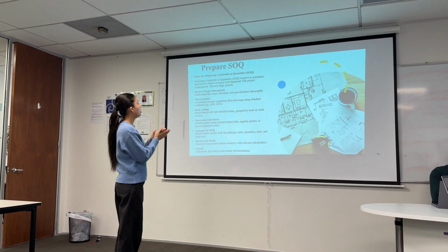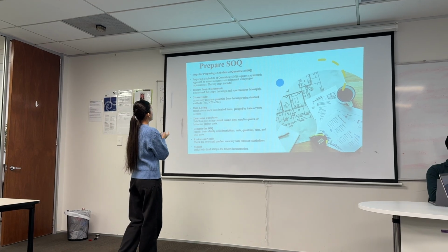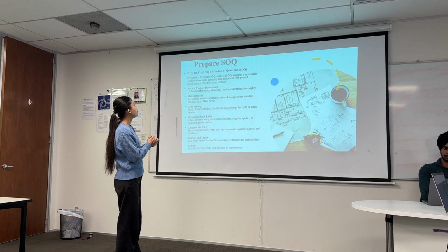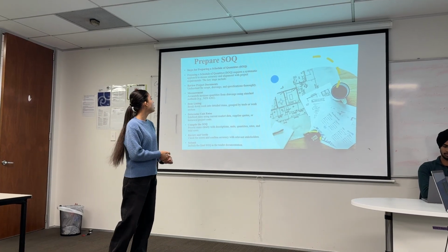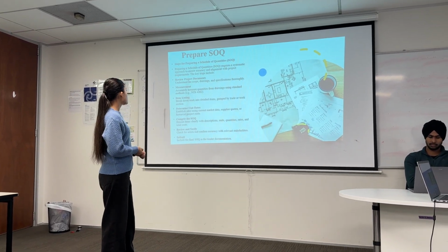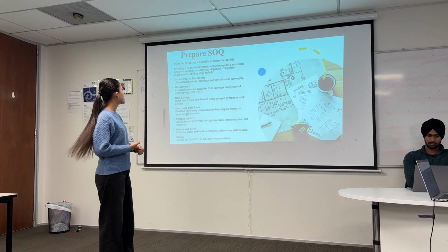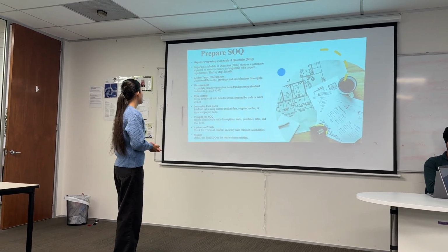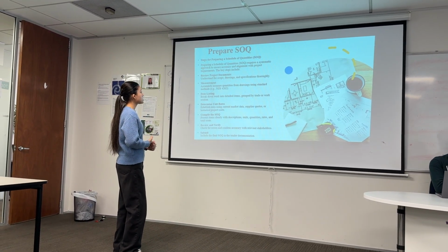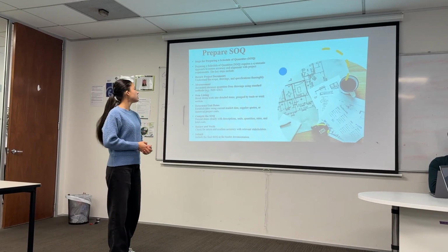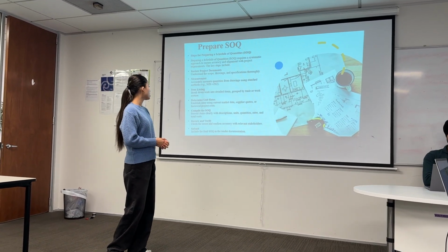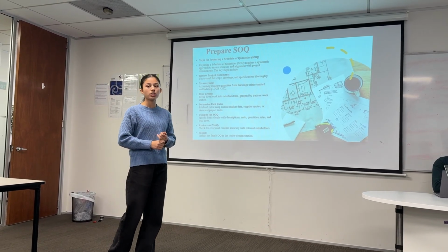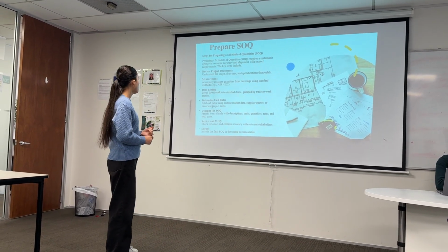First, we will know about what is SOQ. Preparing a schedule of quantities, which is SOQ, requires a systematic approach to ensure accuracy and alignment with project requirements. The key steps include: review project document, understand the scope, drawing and specification thoroughly; measurement, accurately measure quantities from drawing using standard methods; and as